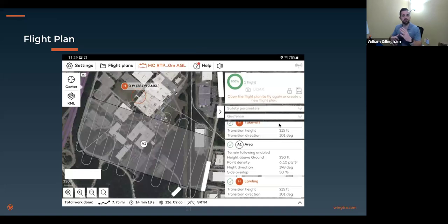Then as it goes into takeoff and flies through the air, it uses in tandem the dynamics that are experienced and various offsets from the gravitational G vector pointing down to estimate your pitch and roll. It uses a number of different smoothing algorithms, well beyond my pay grade, to make sure the trajectory being estimated and applied to correct for any drift over the course of the flight is well accounted for.